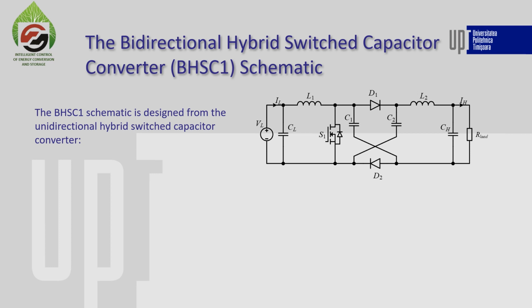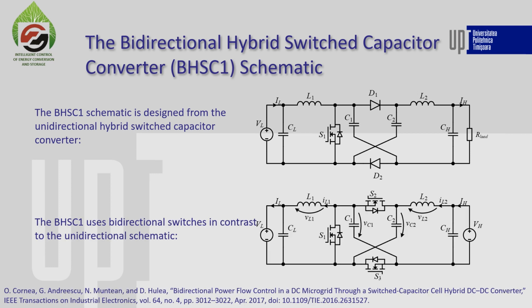And the proposed bidirectional hybrid switched capacitor uses bidirectional switches in place of the diodes. We have these two MOSFETs which replace the diodes. We have therefore bidirectional operation.